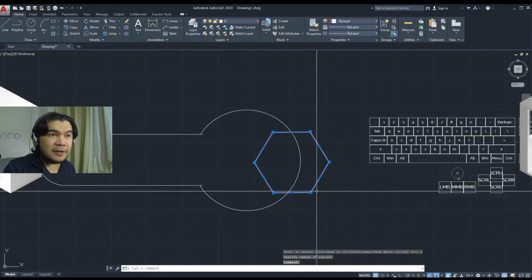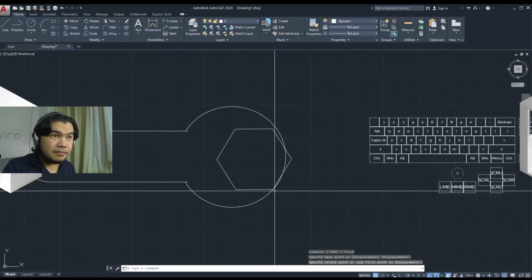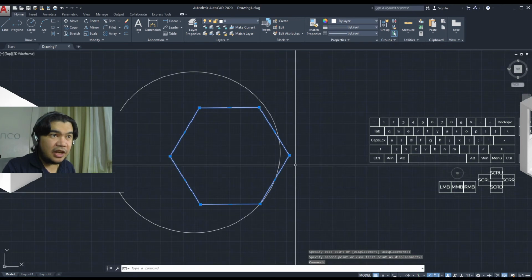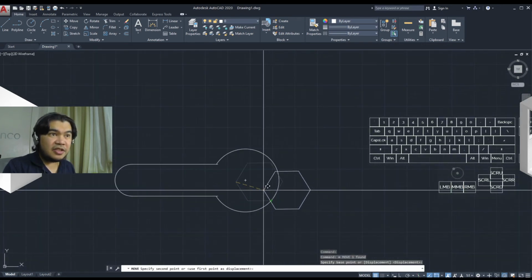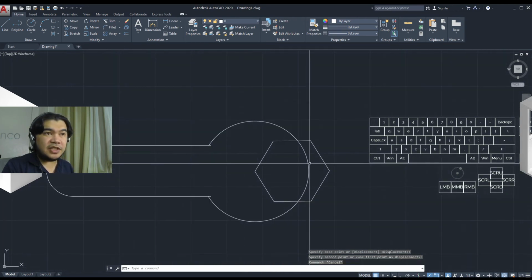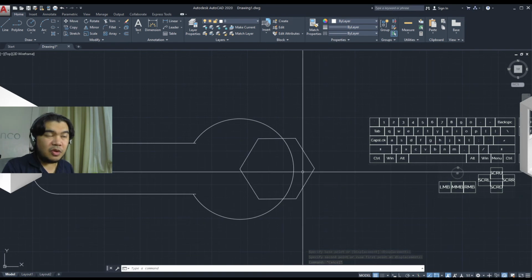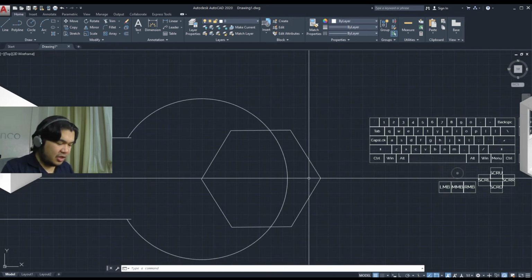So we'll push it in. Let's just align this better because we can. This is CAD after all. So yeah, it's in the center now, and we want to remove all of these, and we'll do a global trim command to do it quickly.